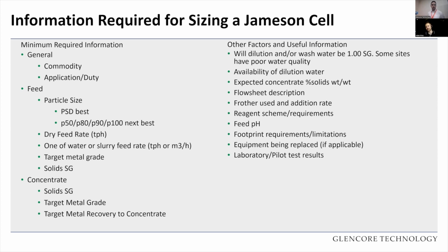What the availability is of dilution water to the feed. This can be important, particularly for cleaning stages, where dilution water can play a part in the sizing, particularly for allowing for feed volumes. If it's known typically what concentrate percent solids will be formed, this can be important for your wash water addition. So again, targeting that one-to-one replacement of the concentrate water that's being produced.